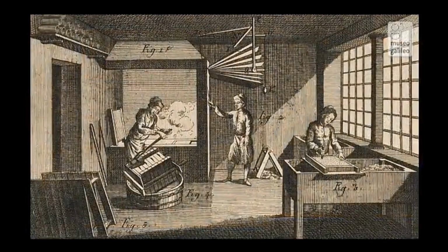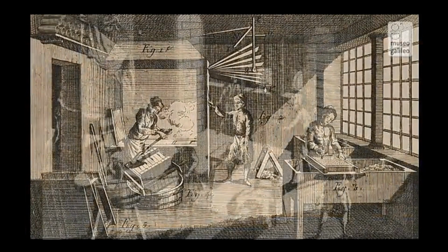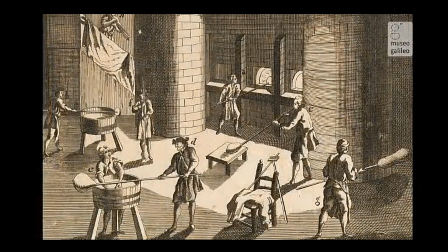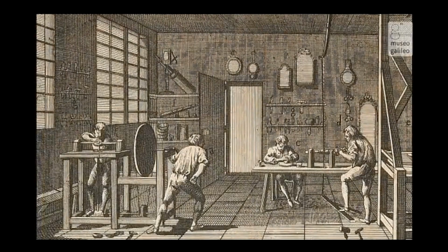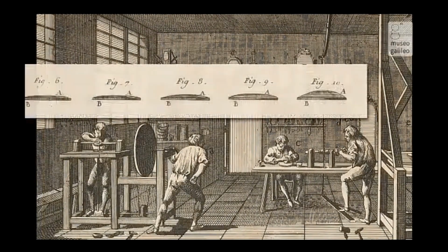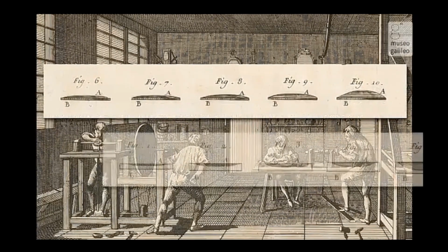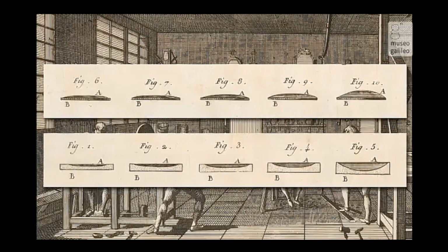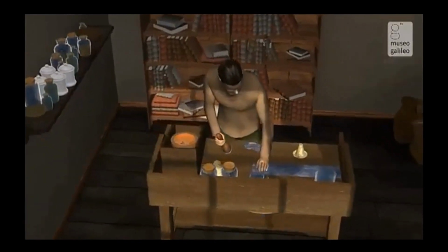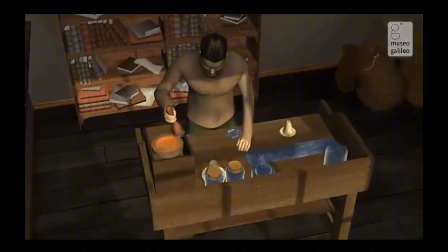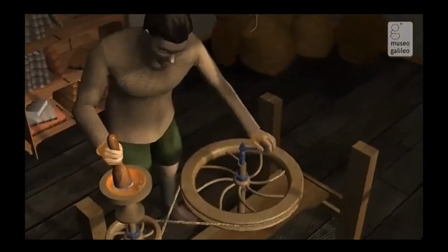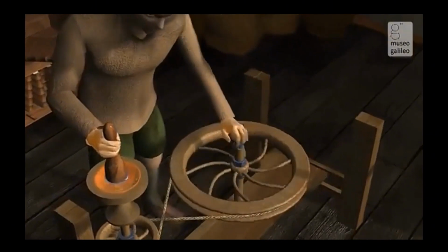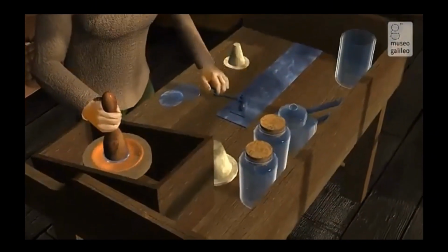The glass was made by melting siliceous sand with soda and other ingredients. A disc, called a blank, was cut from the block of glass, and its edge was shaped and smoothed. To produce convex lenses, concave lenses, or other types of lenses, the disc was ground with a metal bowl whose surface was of the desired curvature. Abrasive damp emery powder was applied between the glass and the bowl. Other, much finer powders were used for the final polishing.